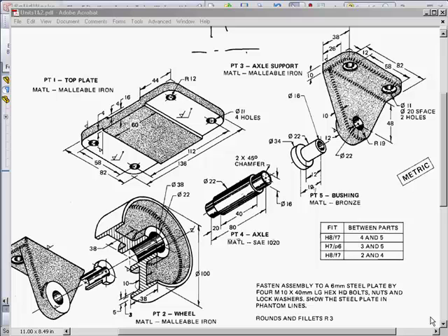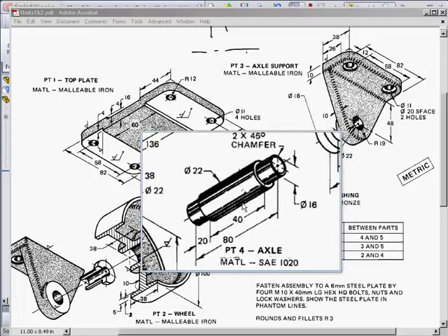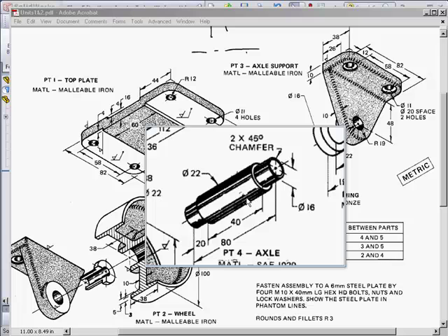This video involves creating revolved parts for the caster assembly that's part of the SolidWorks parametric modeling class. I'm going to start with a nice simple one, the axle. Let me magnify that. The axle is a solid part. It's a revolved feature, and it's clearly symmetrical, both around the axis and end to end. So we have two kinds of symmetry here, and that's important.